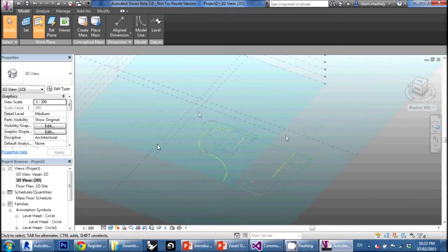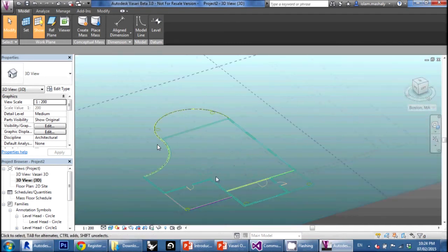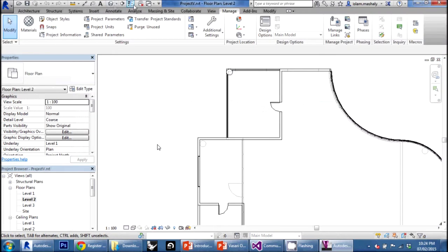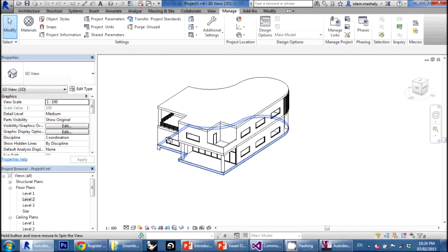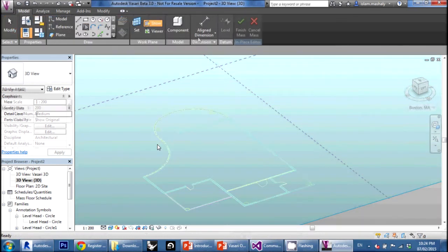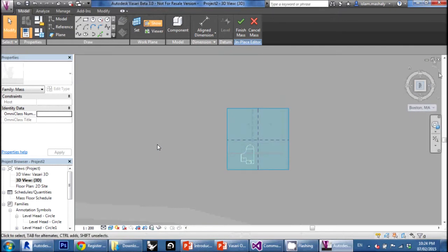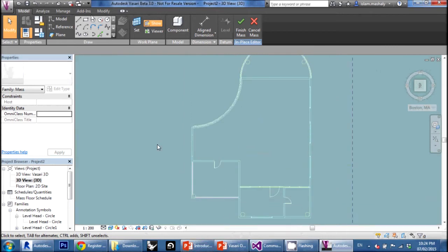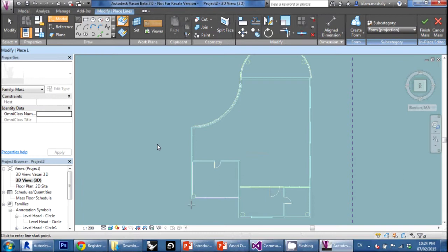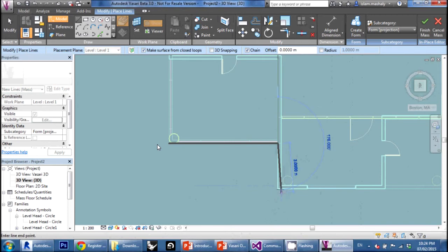Okay, so this is only some lines for the plan of the Revit file, which is this one. And we're gonna start making the mass that looks like this. So first of all, we go to create a new mass. Of course, we're creating something that is unique, and we go to the top view from this box here, and we start tracing our lines on this plan. So we have to make sure that the lines are in a closed loop, as I'm doing here.